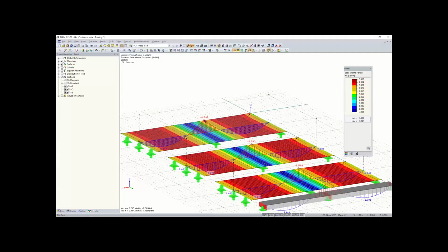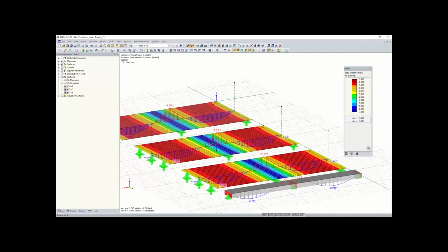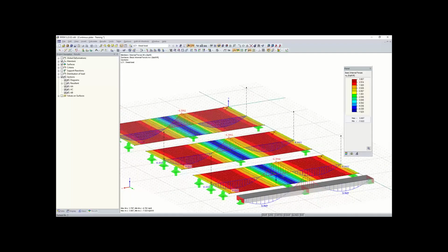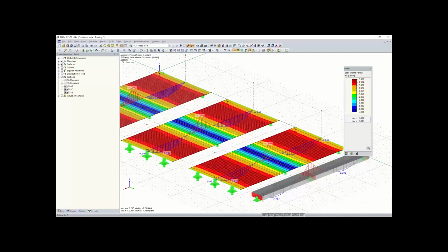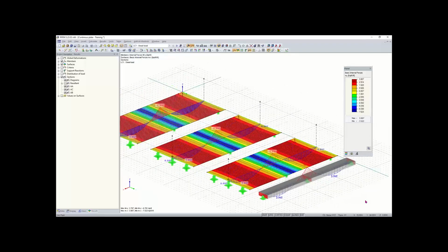So here we get a peak moment of -6.592 for this smaller FE mesh. You can see that increases by just a little bit to 0.593 for the medium sized, and then for the larger size FE mesh we have 0.594. So again, if you get small changes in results like this, the FE mesh size would probably be sufficient for this plate. So yeah, let's take a quick 5-minute break so we can resume this at 11:10.